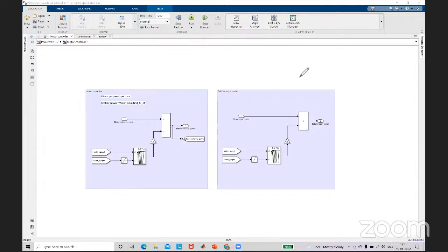The motor controller has capacitors, resistors, and other components, MOSFETs and so on. Whenever you pass some energy through it, they get heated up. Whatever heat they emit into the environment is nothing but the loss. That loss again depends on your motor torque and speed values.